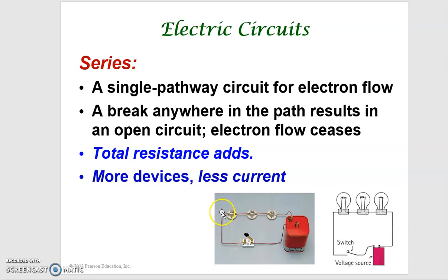it is the same amount of current passing through every single resistor. If people ask you about the magnitude of the current passing through resistor 1, 2, 3, without even knowing the number, you should say they're all the same. The third thing is that each of the resistors has its own resistance, and you can sum all the resistances together in a series circuit.